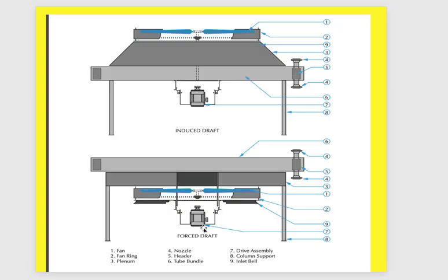The vane hub or blades themselves, this is element number 5. Function: convert rotational energy into air flow. Okay, the blade angle affects the air flow and the power consumption. So these blades work with a special angle, and there is a variation in this angle to increase or decrease the amount of air flow. Adjustable pitch control is available in many designs.